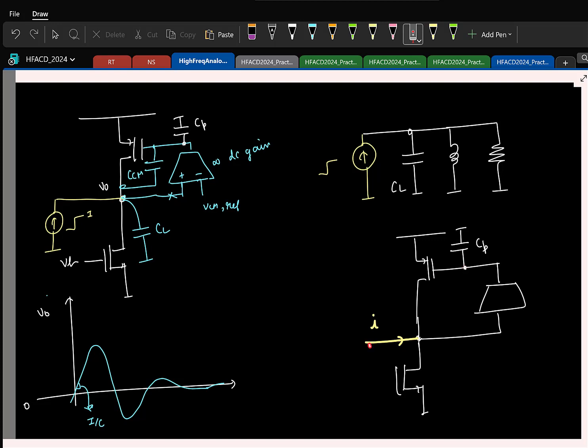And as we saw, if you inject a test current, this voltage increases initially, and the feedback loop should finally increase the voltage. Now, if you have a connection like this, you'll have a delay in this, delay in this. There will be a lot of delay in the loop, and that's why you'll have oscillation. Now if you go and put the compensation capacitance here, if this voltage increases, you don't have to wait for this path to respond. You'll have a conduction through this capacitive path, so that will make sure that the voltage here also increases quickly, and that's what is making the system stable, right?